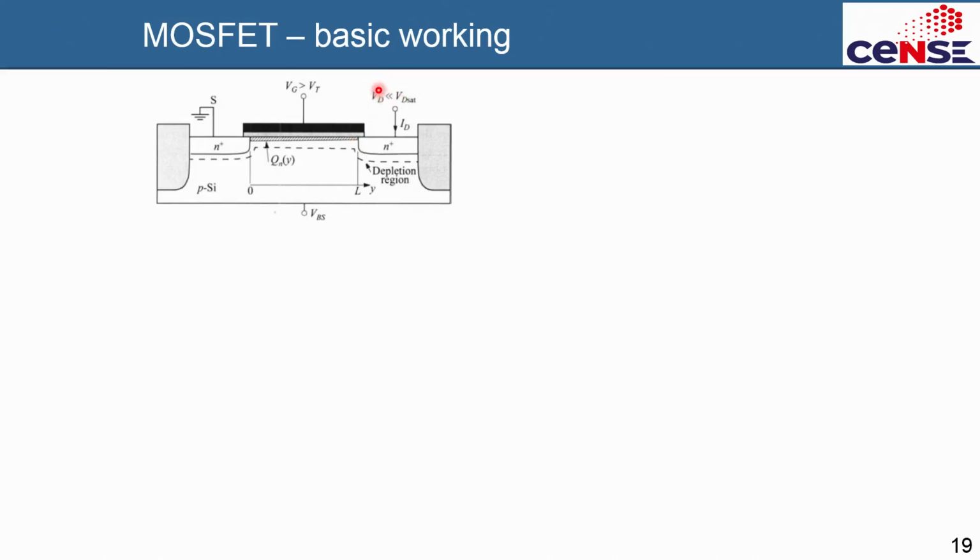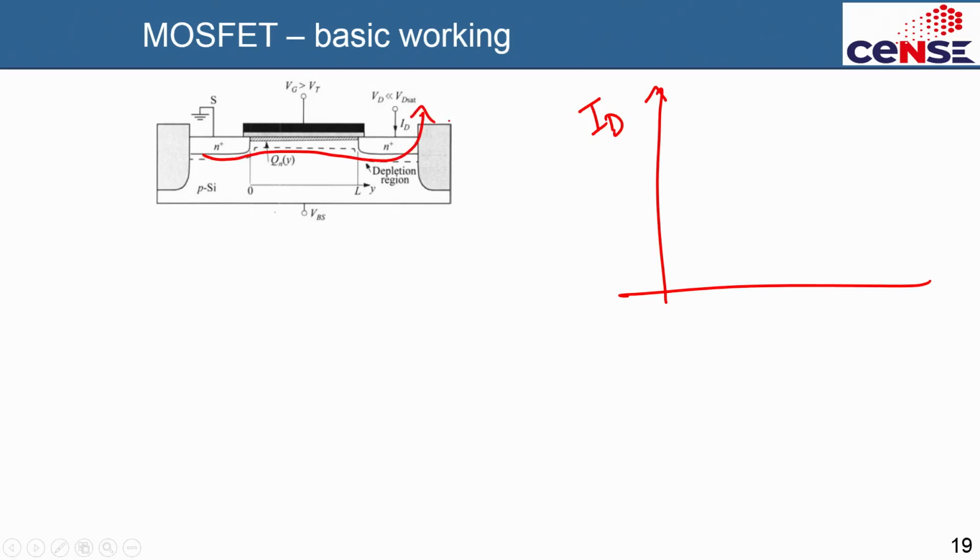So what's going to happen is that if I am plotting the drain current, it is basically the current that goes here. The electrons are actually going like that, so that is the drain current; the real current is coming this side, that is the notion, but the electrons are actually going from the source through the channel to the drain. The channel is already formed, so there is no issue with that. As I am increasing the drain voltage, on the x axis I have drain voltage, I am increasing it from 0 to then 0.1, 0.2, 0.3.